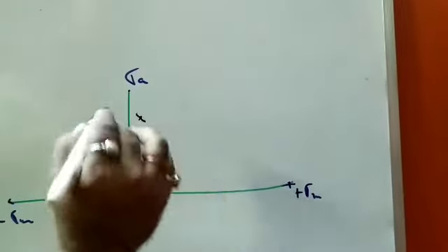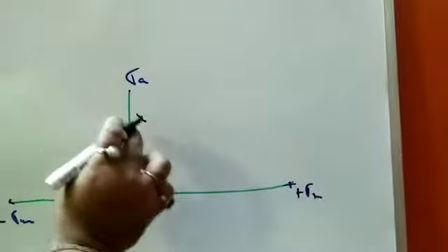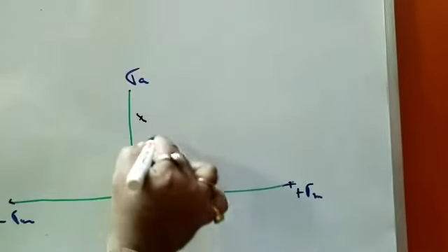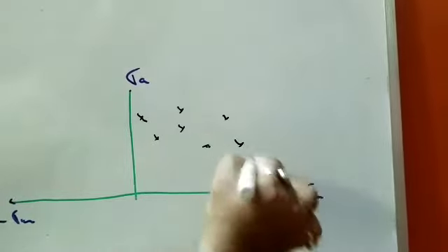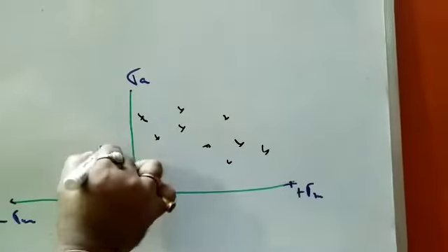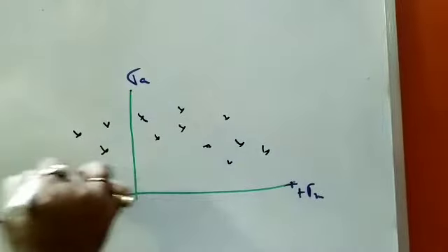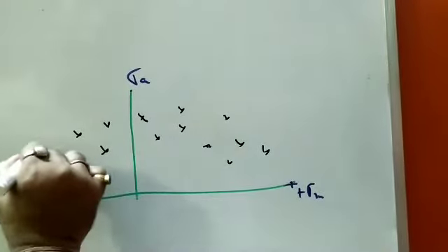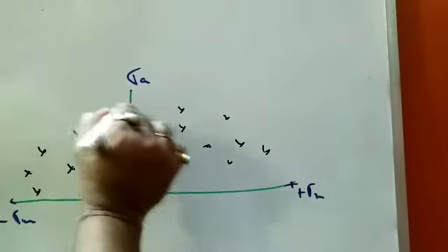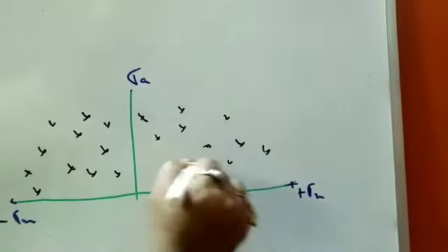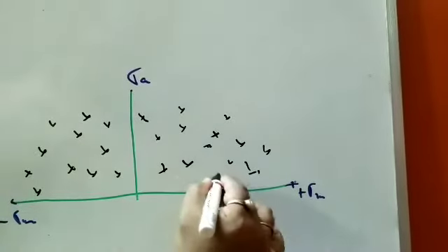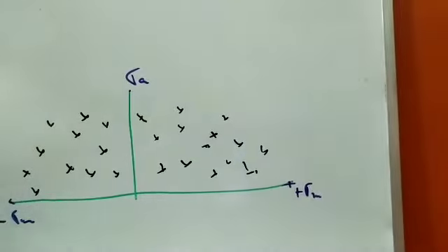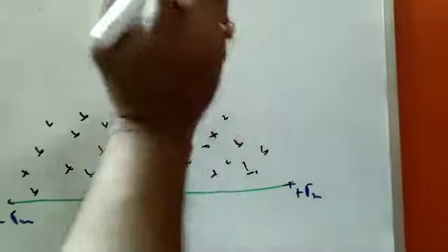So we note the mean stress present and the amplitude stress at which the failure takes place, and we take certain values of the failure points, for both tension and compression. We perform a huge number of tests with many specimens, both for tension and compression, and we have plotted this.